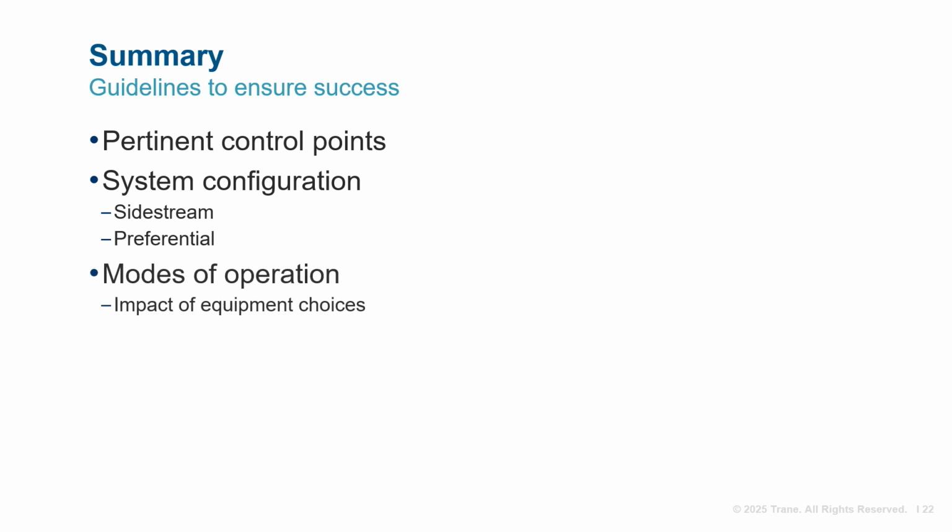And there are bound to be several operating modes based on system needs at a given point in time. Take time to think through which equipment operates during each mode and associated component control required. Pumps may have sizing dependencies related to different operating modes, and chiller selections vary based on system configuration.